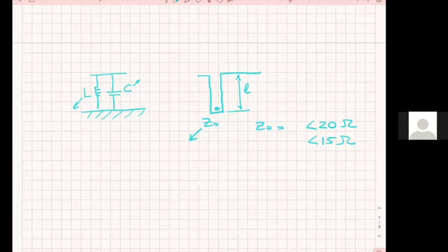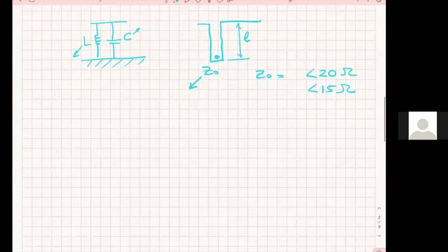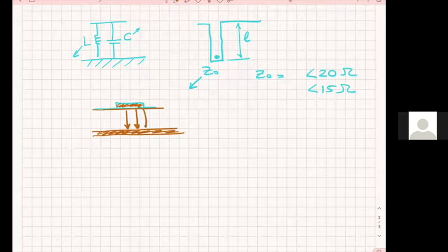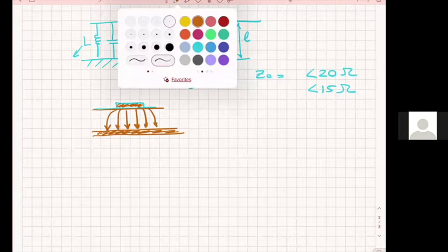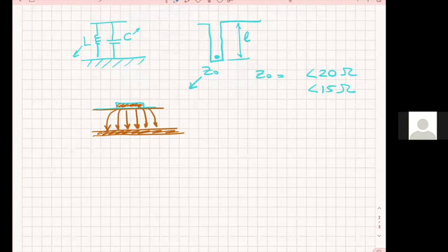That's number one problem. Then your capacitance, which is capacitance to the ground, and usually capacitance to the ground is like here, all right? For a capacitance to the ground, as we've seen before, you rely on this electric field, which is between the microstrip and the ground, to be able to materialize that shunt capacitance. Do you agree with me? Yes. All right.